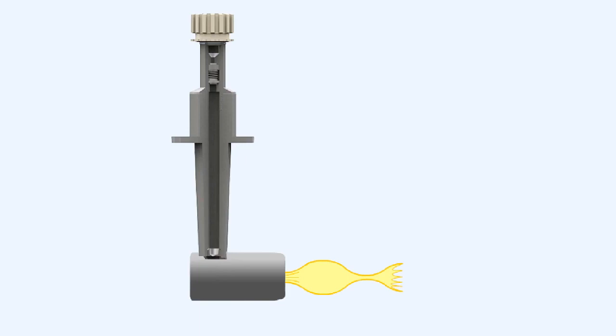At engine start, when there is low engine RPM and low fuel pressure, the fuel spray pattern forms what is known as a bubble. This spray pattern is unable to atomize a fuel jet sufficiently for ignition to occur. As the engine accelerates during the start sequence, the pump rotates faster and builds up more pressure until the spray pattern forms a tulip shape. Atomization is still not sufficient to support combustion. Eventually the pump produces sufficient pressure to shorten the tulip until it touches the orifice. Only now is the fuel jet atomized sufficiently to ensure rapid burning.